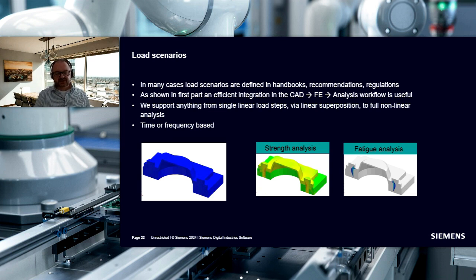Just a few examples here. You see here, in this case, you have a nonlinear analysis of this body. You do a strength analysis of the load-up, and you then do a fatigue analysis on the cycle of when there's pressure inside and outside. So here you get the strength analysis of the bolting, and then in the end you get some pre-stresses here, and this leads to fatigue influences once you cycle the inner pressure in here. So that's a typical example.